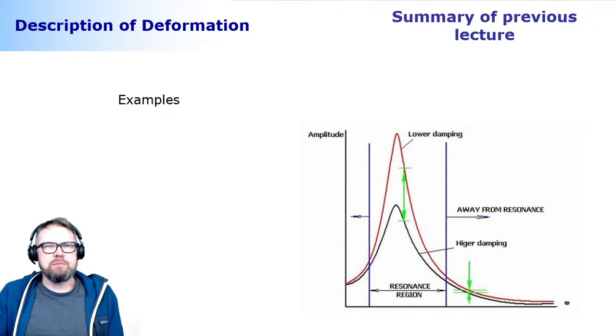Does it create complex eigenfrequencies? Probably, but how to handle that in the case of this floating frame reference formulation is a question that I cannot answer. I haven't really thought about it, because usually the assumption is that the damping is less than the value that affects eigenvalues. And when you make that kind of assumption, you can easily ignore the effect of damping.